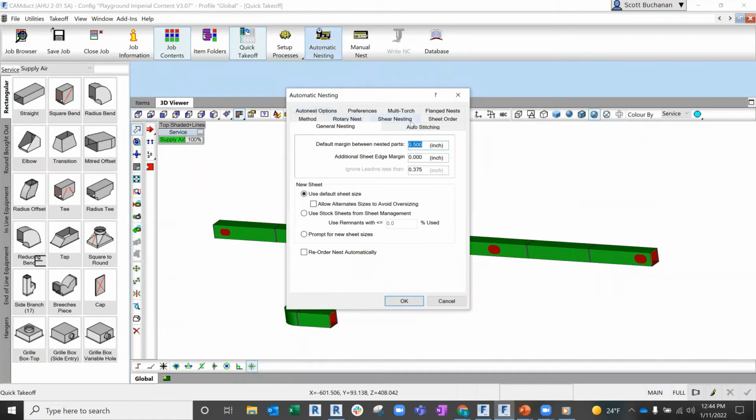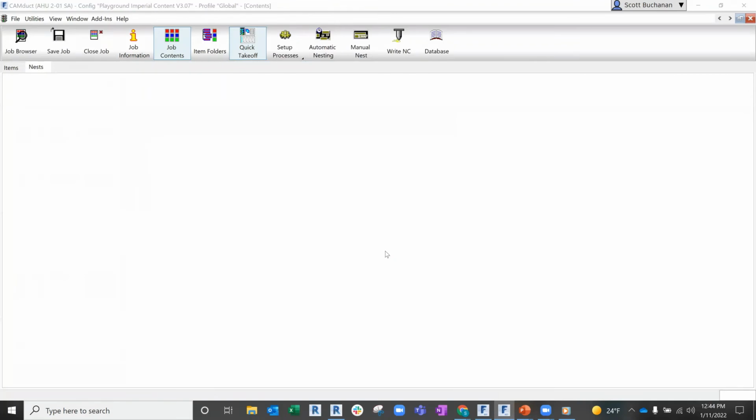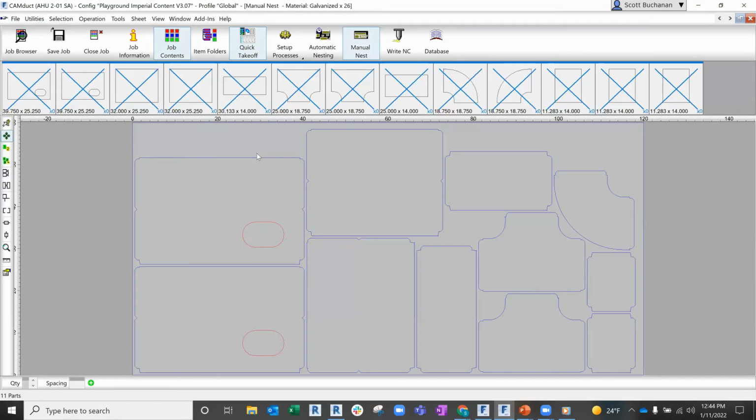So they would have this configured based upon their preferences on the sheet metal, and it's going to go ahead and create and stretch out these flat patterns. So I can see I've got 2 sheets created. If I just want to open one of these manually, I'll close it down in a second. But we can see there are each of those straights. For those that haven't seen it before, the straights are in two parts, right? So there's a folding notch right there, and there's a folding notch right there. Those get folded in twos and get tacked together and all that fun stuff.